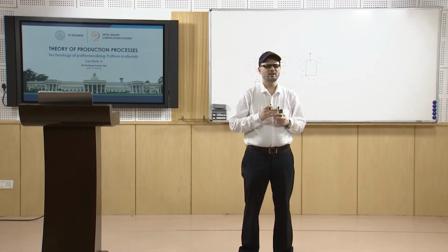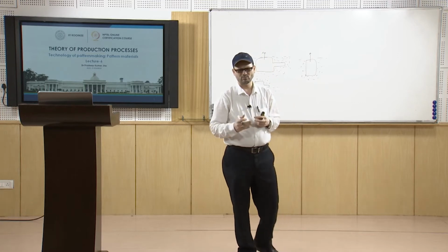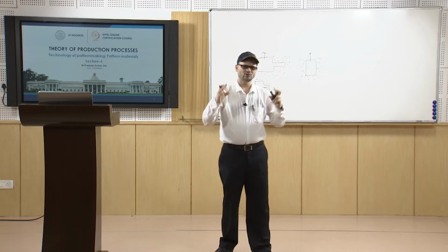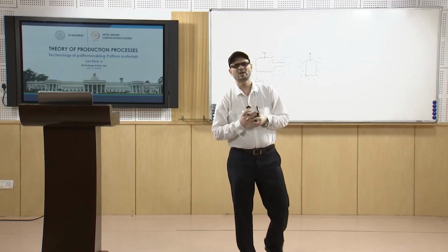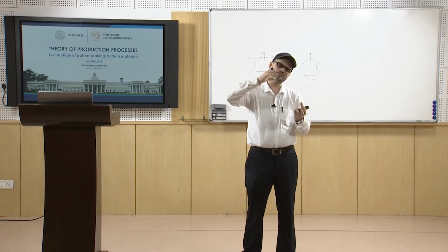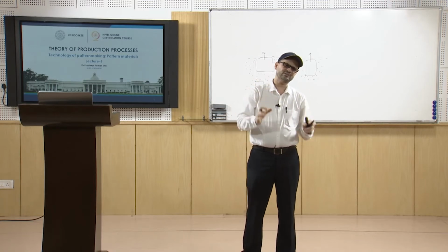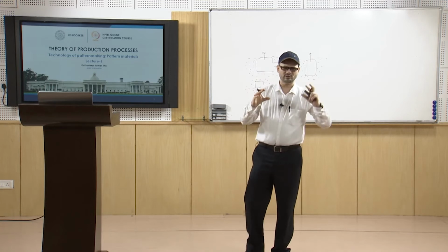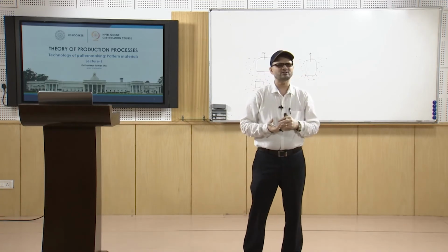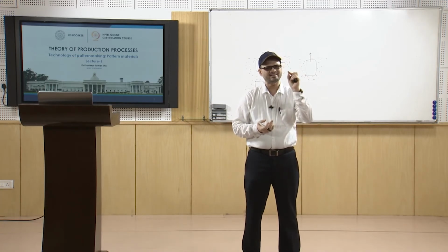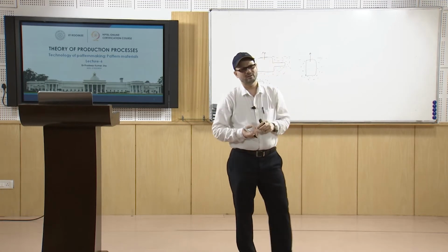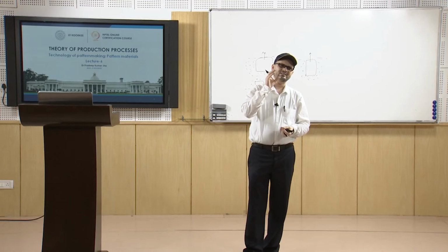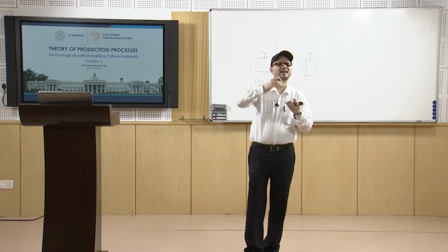Method of molding: you are using manual molding or machine molding, high pressure molding or so, because the pattern is subjected to that pressure. The pattern is kept inside the molding material and then it is also pressed, so it has to sustain that pressure. If it has delicate parts, you have to be careful, and if it has to be rammed, then you have to choose the material in such a way that it can withstand that much pressure.